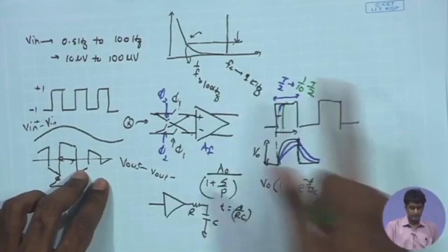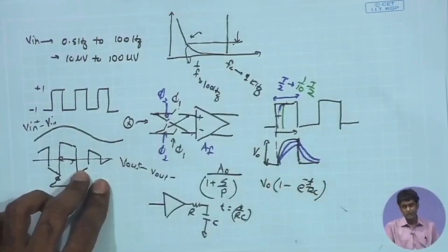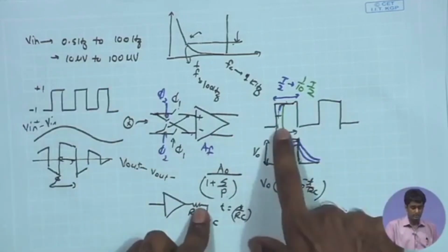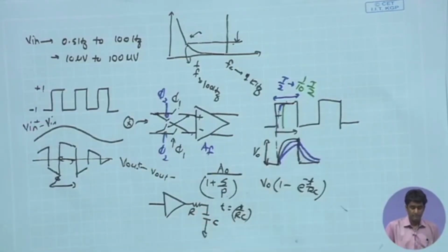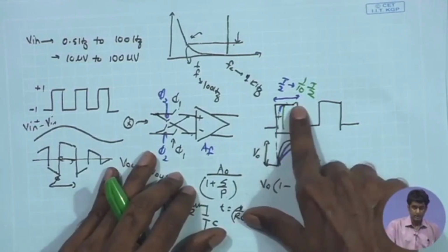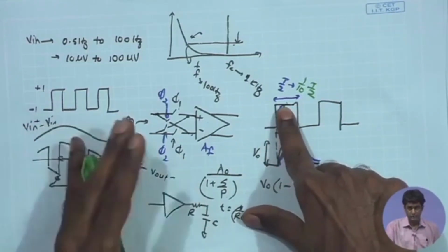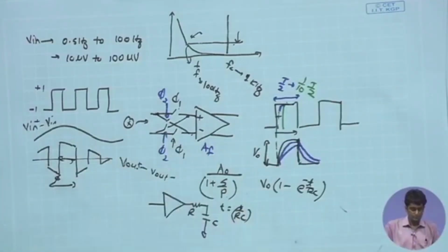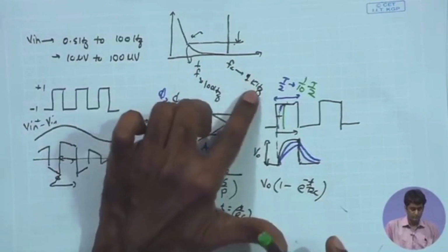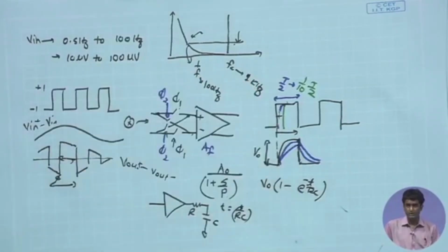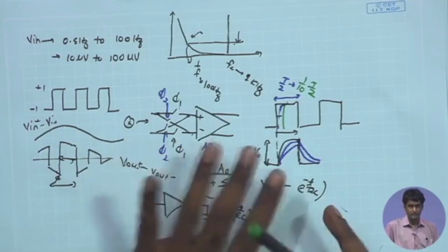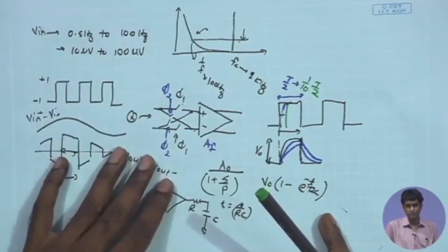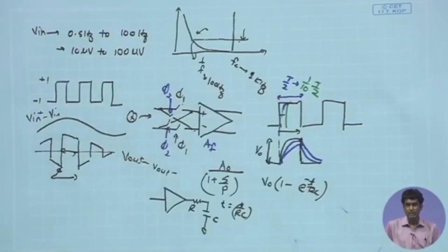frequency. So, if I assume that the chopping frequency has been taken as 1 kilohertz, that would imply that the amplifier bandwidth would be even larger, maybe at least around 5 to 10 kilohertz, to be more conservative, maybe 20 kilohertz. So, let us stick with a reasonable number, 10 kilohertz. So, if FC is 1 kilohertz, let us go for the closed loop amplifier bandwidth as 10 kilohertz. We have discussed this briefly while discussing the chopping operation also, that why do we need to have a higher amplifier bandwidth when we go for the chopping operation.